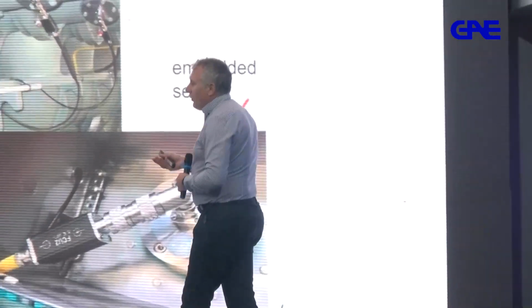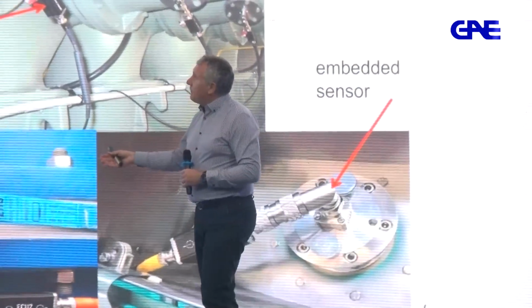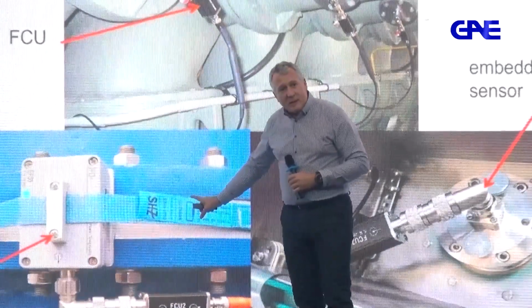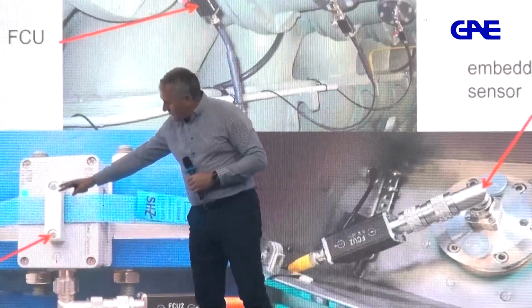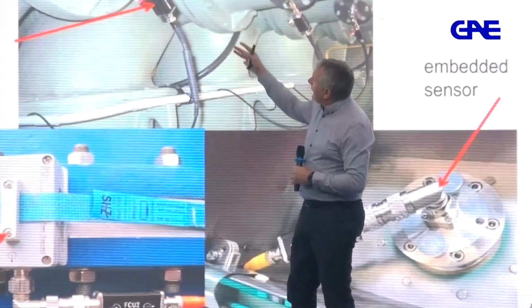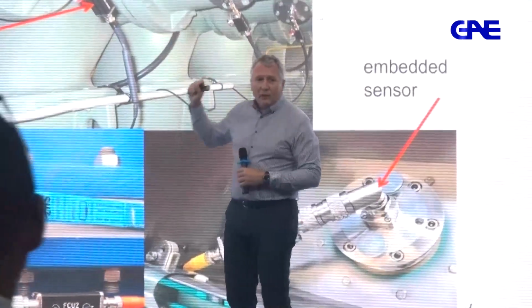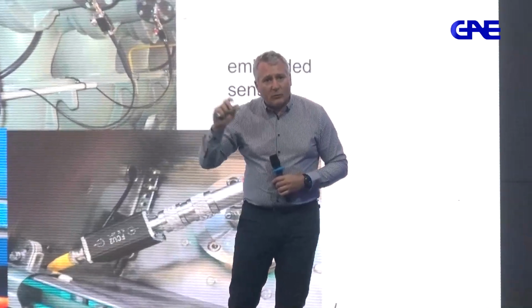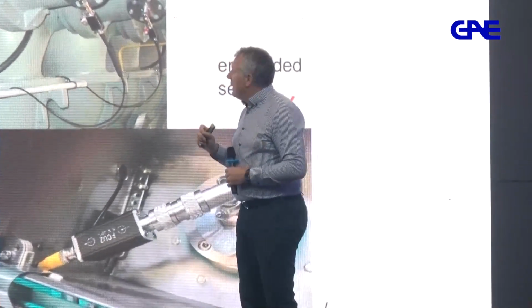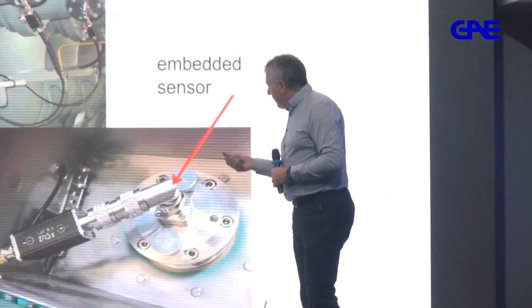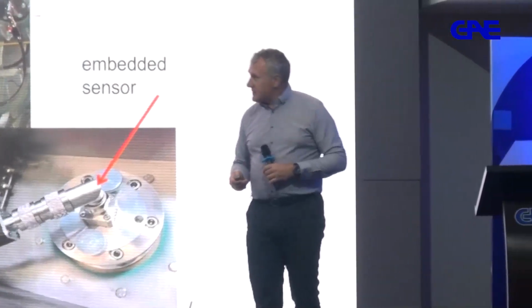When you have GISs, they do not have built-in antennas. So then you will have this epoxy spacer, and you're going to use an external antenna to gather the UHF information. In other cases, you have a hatch window. We have specialized antennas that can be mounted on top of such hatch windows, and tomorrow I will detail such things a bit more. And then, of course, you can have built-in antennas.